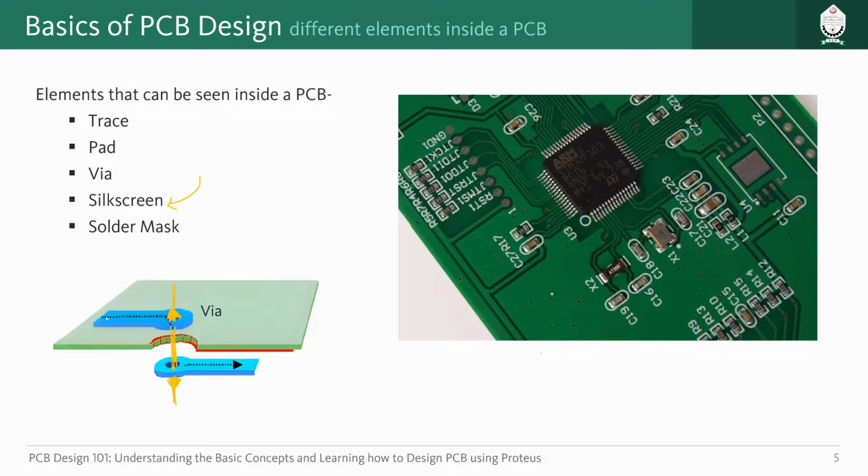So this is insulated, that's why there will be no conductivity here. This is just for protection purpose. We can use solder masks if we want, but traditionally in our country, as this is a costly process and also sometimes we don't have that facility in most of the PCB designing factories, that's why we don't use solder mask. So this is an optional situation basically.